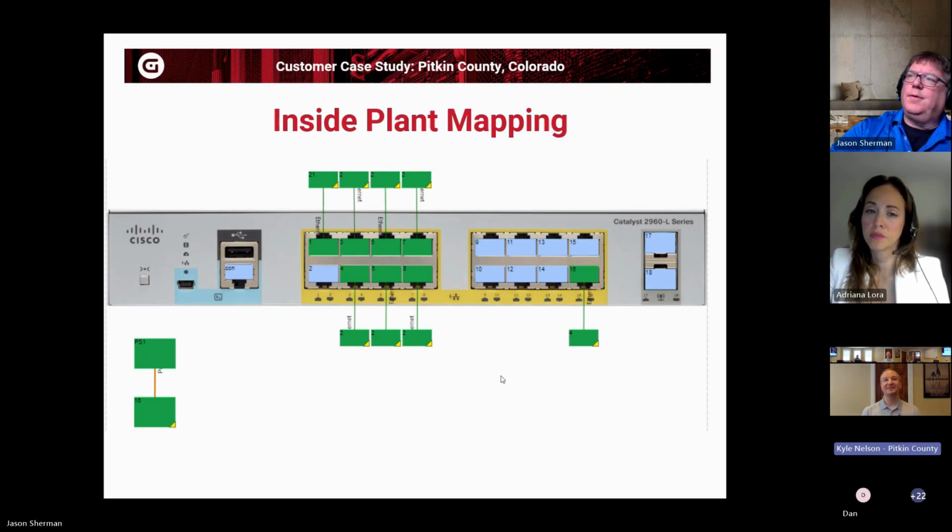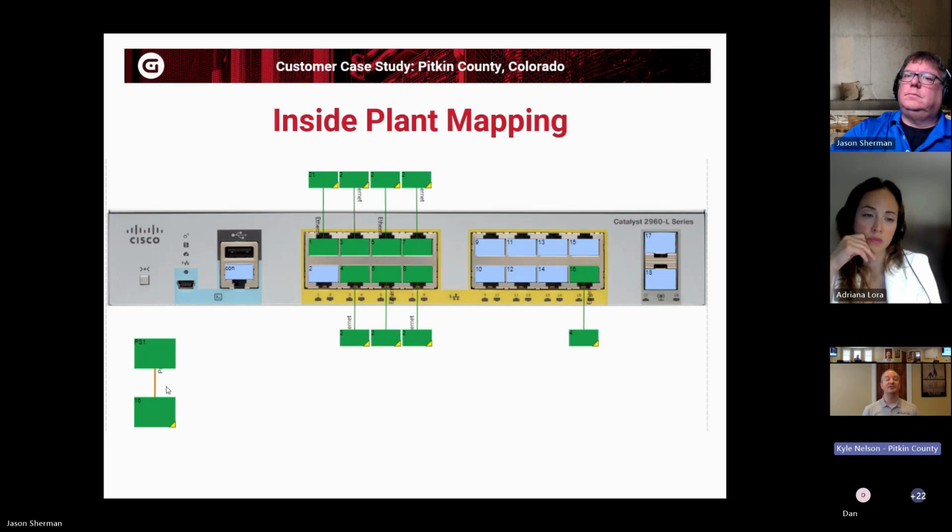There's, at this point, not quite any visual override, no rhyme or reason to it. That's just the default that we kind of started with. Gotcha. Like Ethernet connections were green, so the small lines between those larger port rectangles, right? That's just knowing that that's Cat 5, Cat 6 Ethernet cable, and then our power cable for 120 volt power is there in orange, just so that we know, because we also operate a 48 volt system for some of the devices at our sites that are battery backed up that we'll see in just a second. And so we can then know, is this grid power or is this backup power that's making this connection?